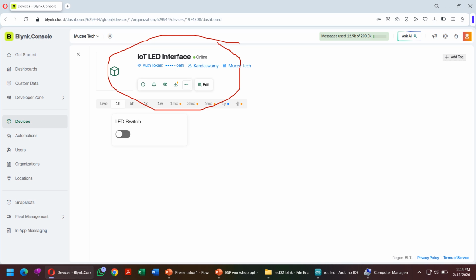So once this is okay, there is connectivity already made between your web and your 8266. So initially you configure the web page, and then later you configure your Arduino compiler with your ESP8266 port. The same procedure can be followed for ESP32 also, but choose ESP32 instead of 8266.